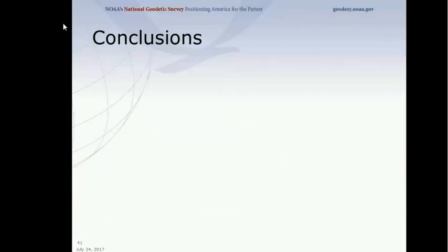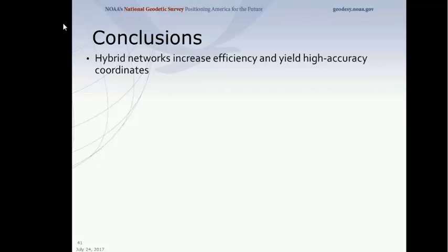So to kind of wrap this up, I'm excited about this technique. Hybrid networks definitely increase efficiency. The field work is doing the RTK surveys, and then you take advantage of the data from your active stations to do your static processing.